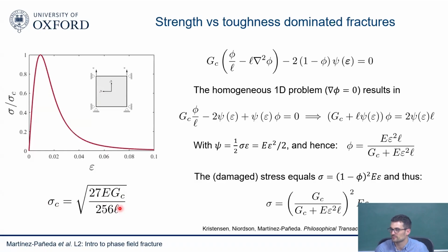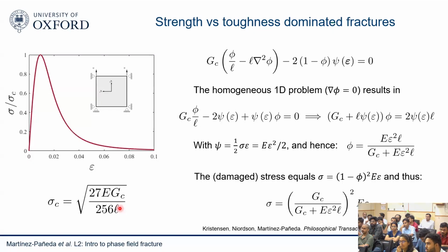Usually in ductile materials, the fracture process zone is smaller. But if I talk about quasi-brittle material or something like that, in this case we have a sizable fracture process zone. So should L then be higher, and can we take some number of elements inside L or something like that? Is there any relation between L and element size?